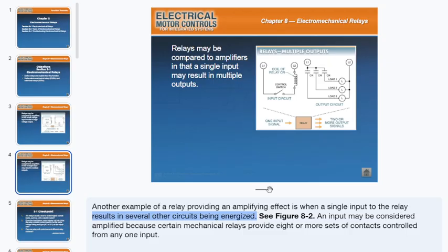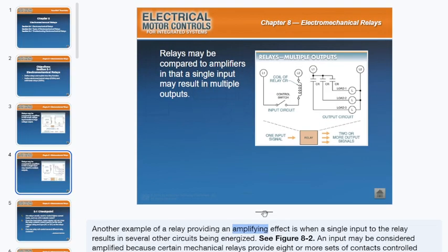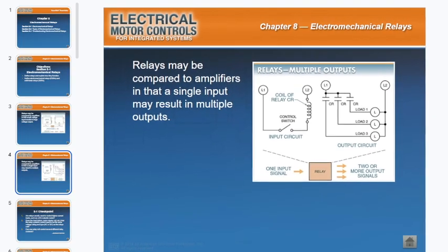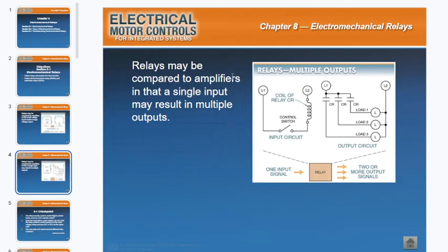So this kind of acts as an amplifier. This is why they're using the word amplifier. It's in the loose, way loose term of the word amplifier. Right? It's just not an accurate use of the word amplifier in a sense. So a single switch can result in a bunch of contacts energizing a bunch of loads. And this gives us an advantage.